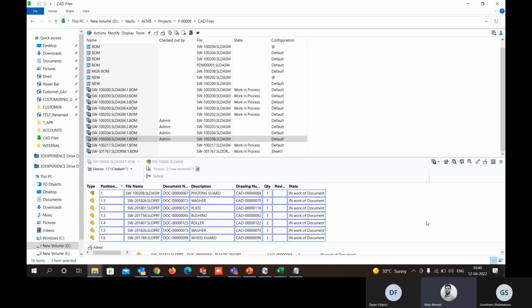So what we are saying is that as of now, we will not set up any process for BOM approval in PDM, and we will wait. No, that's correct. And we will implement the process. Yeah, that's what I meant. Here, you need to do an extra thing: you're going to save this BOM as a bill of materials in manage directly, which you're going to get from the PDM assembly. There directly you can add, and you can have multiple bills of materials as per your standards. Like for the machinery, one bill of materials, and you can have multiple bills of materials. Directly you can add those external files also. That is very convenient, I can say.